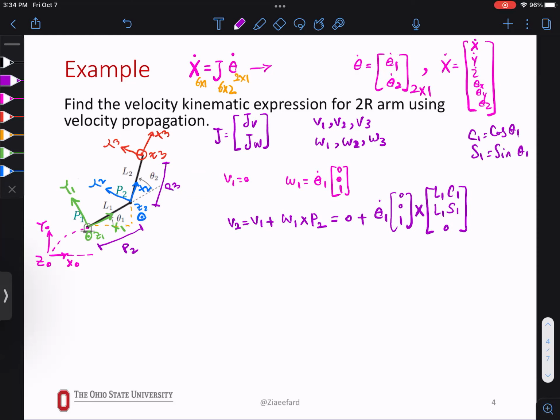All right, now, I don't actually have to do this. You can use a skew-symmetric matrix if you wanted and solve that. When you're using your code, you don't have to actually do that. It will do it for you. So I found V2 and omega 2. What is omega 2? Omega 1 plus theta dot 2 multiplied by the direction 0, 0, 1. So what is omega 1?